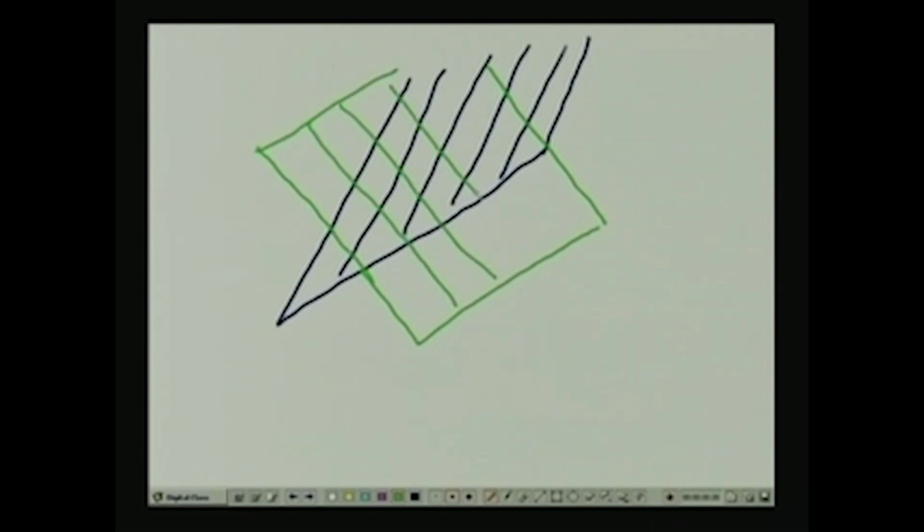So these are the two joint sets that we are dealing with in this particular problem, but here the tunnel is moving, rather than being parallel to the strike of the joints, it is moving perpendicular. In this case, the problem of rockfall is going to be much more limited.